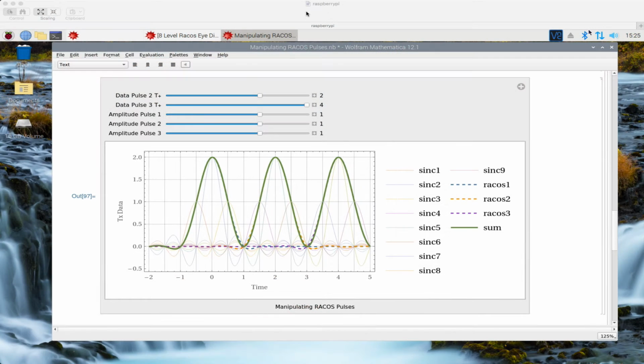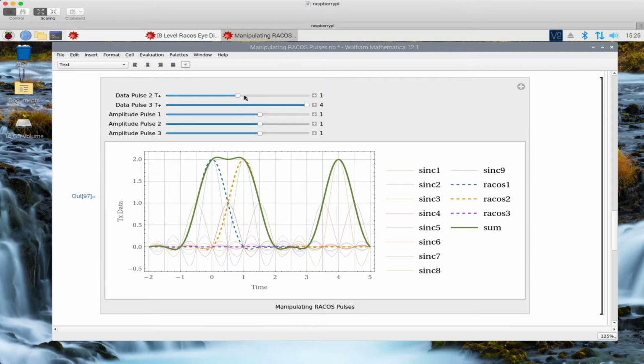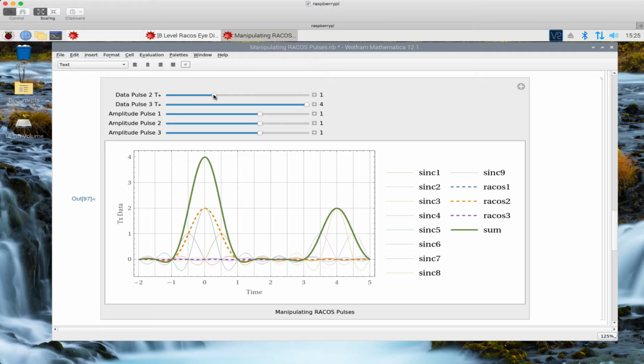Most digital communication systems use binary signals where one bit is encoded into one of two levels. Nyquist channels can increase the effective bitrate by supporting amplitude modulation to encode more bits per symbol period. 2 bits requires 4 amplitudes, 3 bits require 8 amplitudes, and so on.